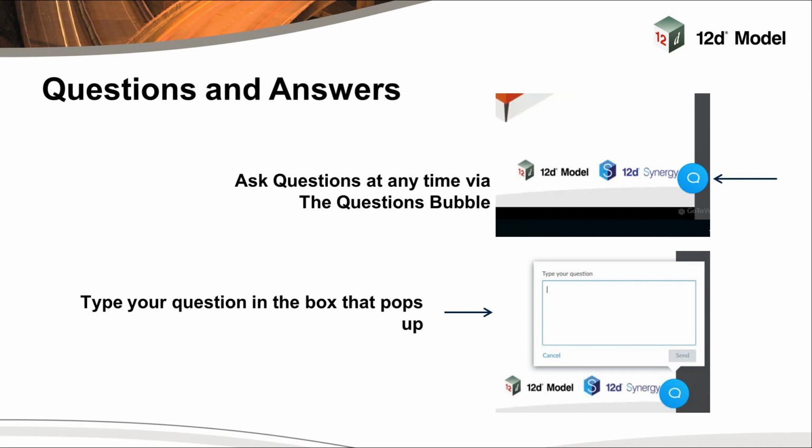Sure. One from Nkomo Zumbango said, please confirm that I can use MPS for plotting cross-section views, and is it possible to plot these onto a view rather than PDF plots? Not if you're using the MPS. So the cross-section views, you will be just referencing the exact same plot parameter file that you've set up for the cross-sections, and that special chapter inside the MPS will just produce exactly what's set inside that PPF file. The title block is taken over, and the title block information in the PPF file is ignored, and that's totally controlled within the MPS.